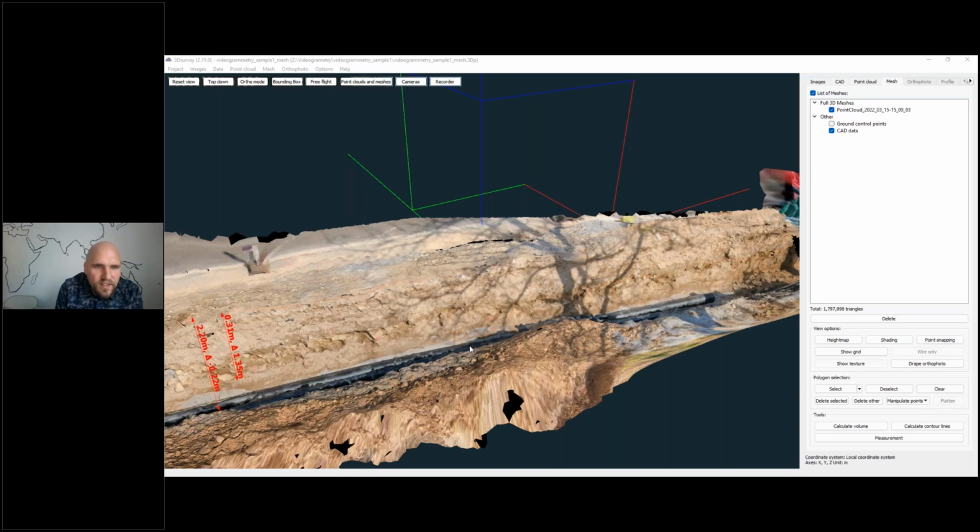Mr. Ditya is asking, does the DJI Phantom 4 RTK UAV use video coordinates to read in real time? I think there is also an option on the DJI Phantom 4 RTK to write the telemetry information in a special file, but that file is slightly tricky to synchronize with the video. So maybe that can be done, but with Phantom 4 RTK, the best approach would be to record some photos. Each photo will have the very accurate RTK position in EXIF, and even if you add some video next to that, the photo RTK positions will georeference the end result quite nicely.